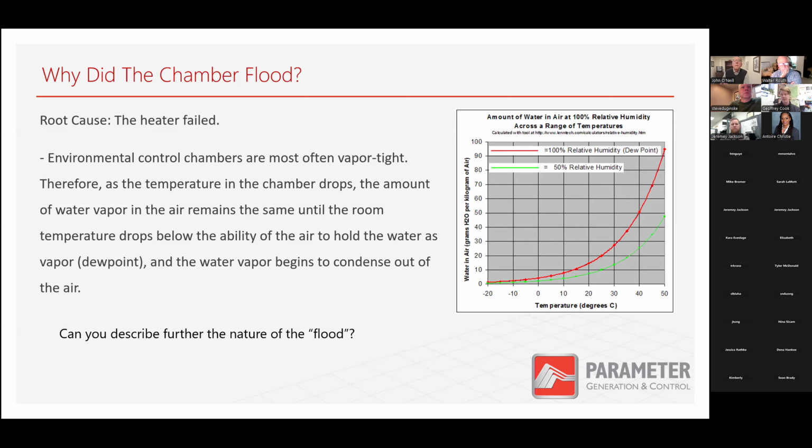At the very least, the entire inside of the chamber should be inspected and cleaned. I would hope that a heater with a risk of imminent failure would be observed through that process, and you could note that it may need to be proactively replaced to prevent that failure.